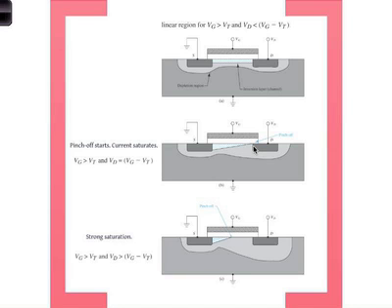Similar idea, but slightly different physics. The other important thing, of course, is that we have a threshold voltage, which means that there is a minimum voltage that needs to be applied to the gate before an inversion layer can be formed. Okay? So the transistor doesn't operate for a while until you reach some threshold. That's a very important parameter for a MOSFET.